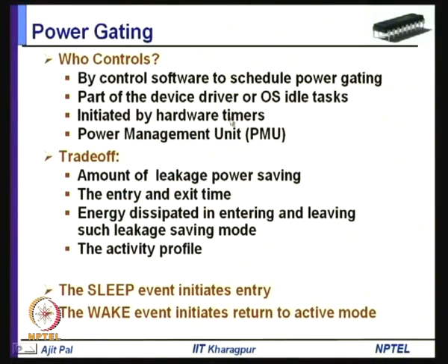So, the idle situations can be found out. Another possibility is it can be initiated by hardware timers. Inside the processor you will find some hardware timers known as timer counters. For example, you want a particular event to occur after a certain time, and that time can be programmed, and after that time is over, that timeout is reached and that event is triggered.